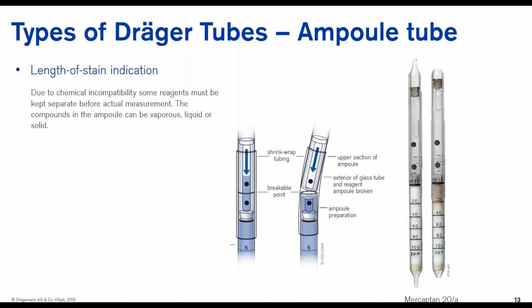You break this ampoule using the tube cell, looking at the two black dots, and break in the middle. When you break it, the liquid of the ampoule will transfer to the indicative layer and be carefully drawn through the pump itself. After completing the measurements, wait for the measuring time prior to evaluation.